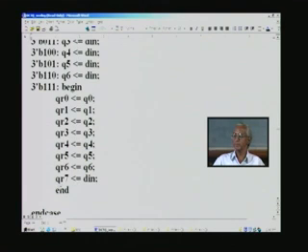So, these partial products which we have written, if they continue to be in the same Q0 register, with the arrival of the next clock, that is the 9th clock, this Q0 will be overwritten. So, the partial product will get lost. In order to avoid this, remember that we need the partial product for the computation of the next stage, for which you need a further 8 clock cycles. So, that means this partial product will have to be stable for the next 8 clock cycles.